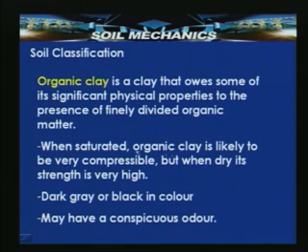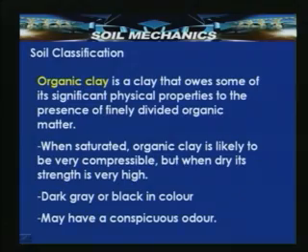When saturated, organic clay is likely to be very compressible, and when it is dry, it exhibits very high strength. The dark grey to black color is an indication, and it may have a conspicuous odor.